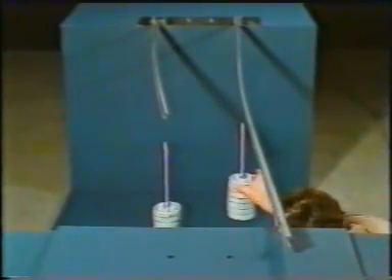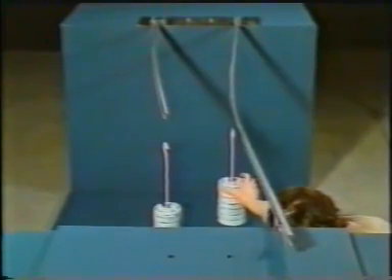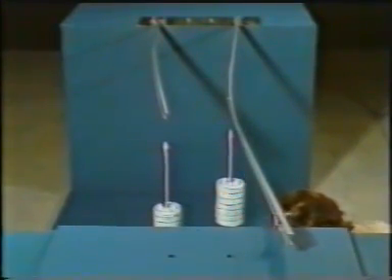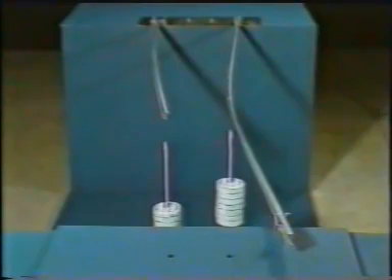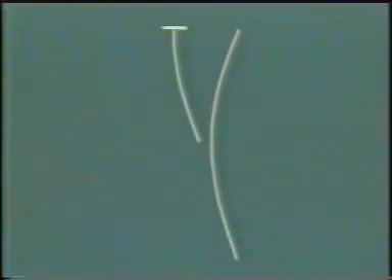Again, failure occurs due to instability. It can be seen that the distorted, buckled shape of the cantilever is approximately the same as either half length of the simply supported beam. Viewed from above, the out-of-plane deflections of the cantilever and either half length of the simply supported beam are obviously similar.